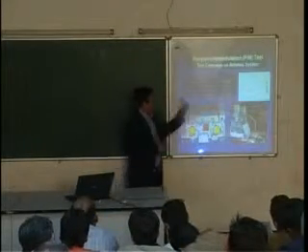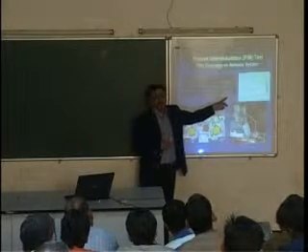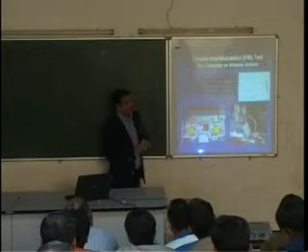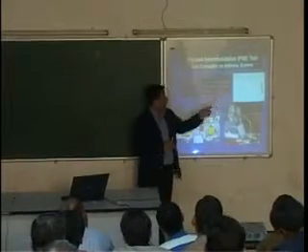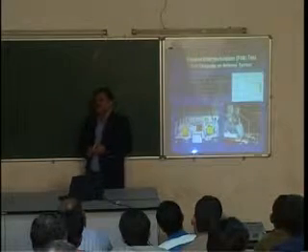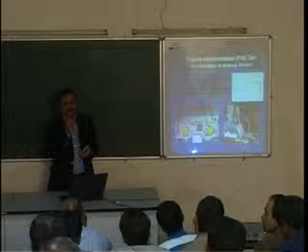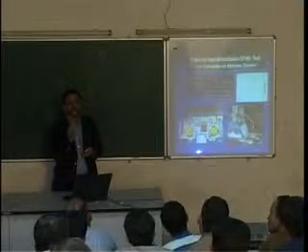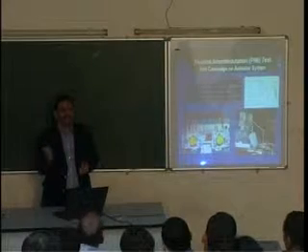We have to calibrate the system, the minus 140 dBm signal, so that it can measure PIM as low as minus 200 dBc. You have to measure this because a very minute signal can create havoc in the spacecraft, or even in your ground segment.